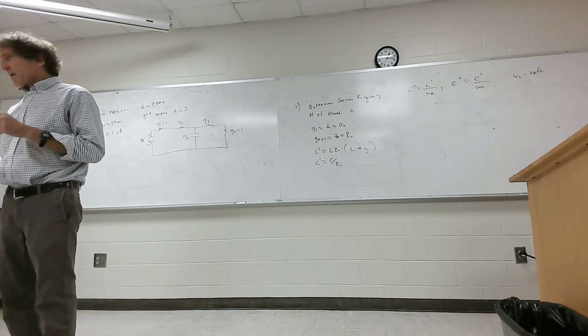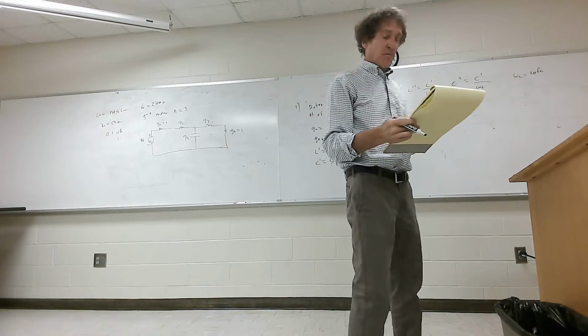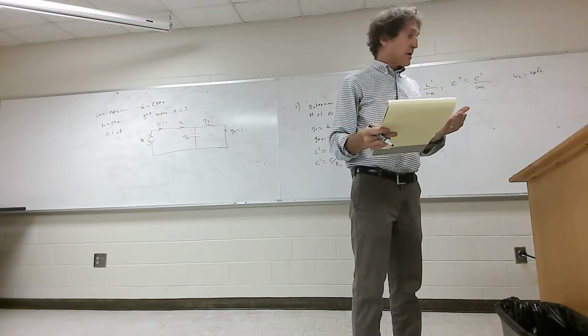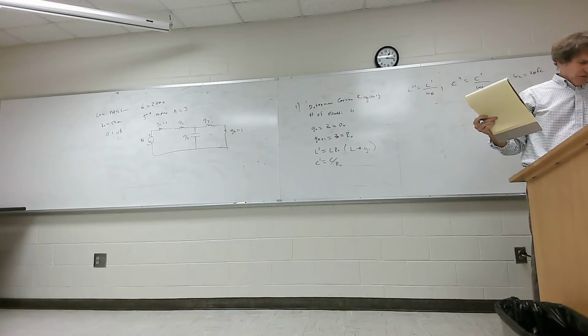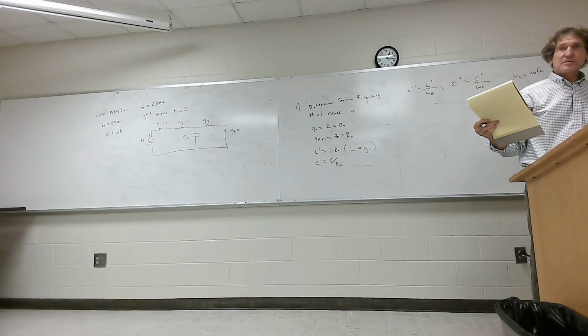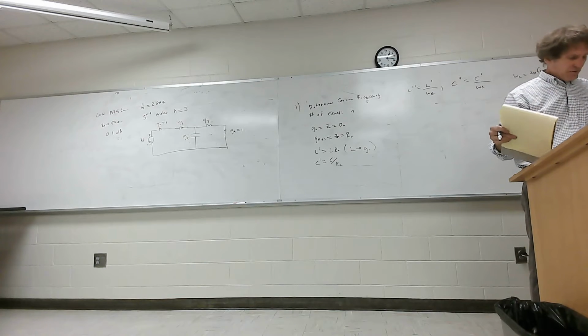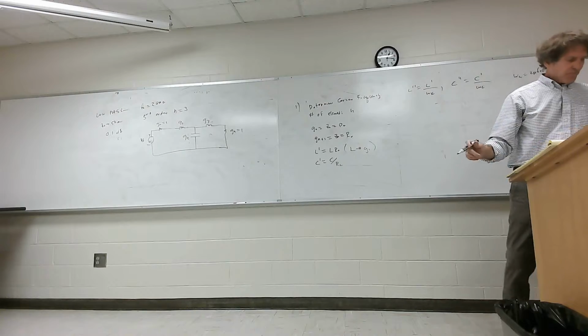So if you look in there at 0.1, where you want 0.1 dB of ripple, it's the bottom. Can you all see that? In my figure, it's on top. Is that right in yours, guys? 0.1 dB? Okay. Now, if you look down there, the number of elements, n equals 3, and you look over, you get values.